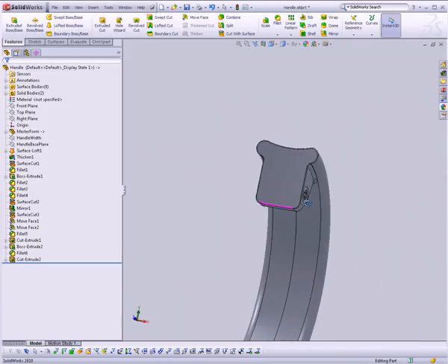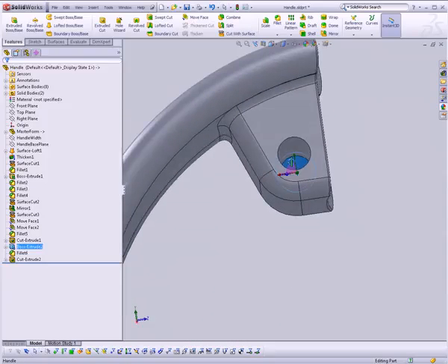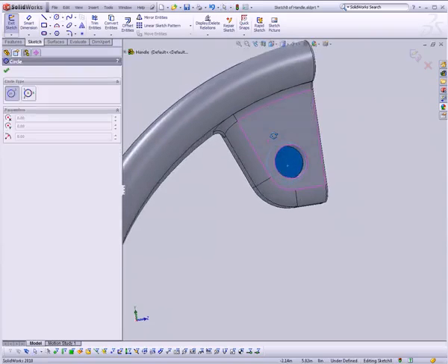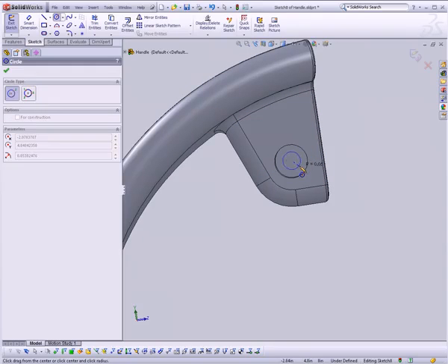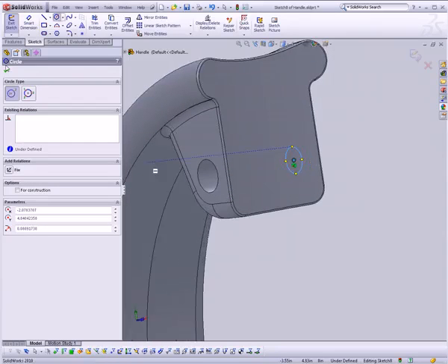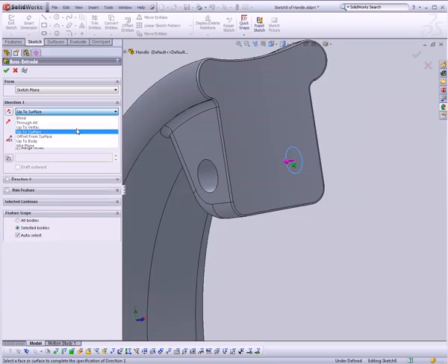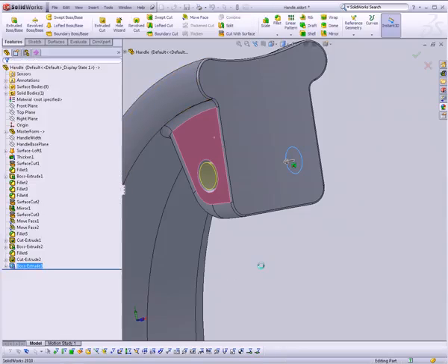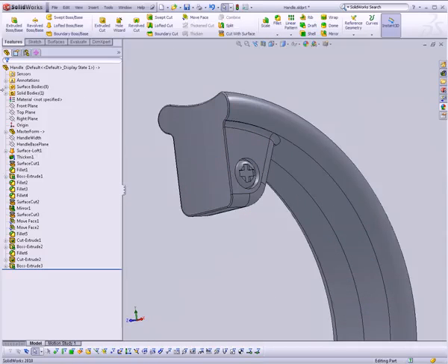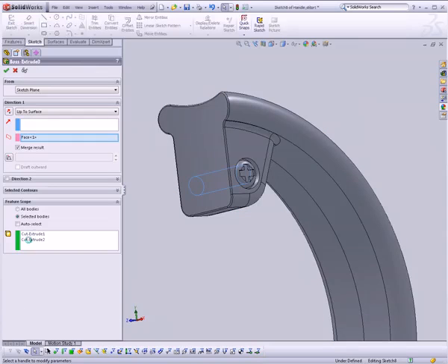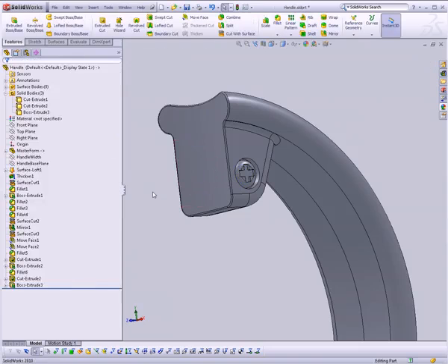We'll just have to put the other side of the screw over here. So we'll do an extruded boss, once again with a circle, back on this back plane, and then bring the extrusion up to surface. Just choose this surface. And that'll work well enough. I think we still have a separate solid body, right? Oh, nope. What did we do wrong? There we go. That'll work.